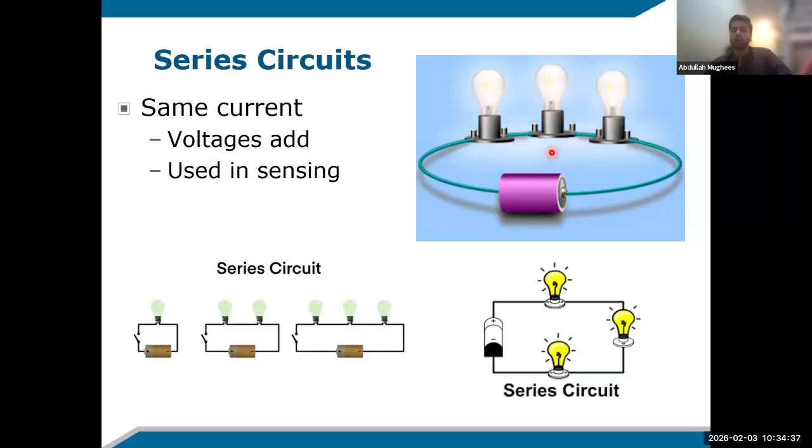All of the things are connected to each other, and they all glow perfectly with the same brightness. But the problem with this series circuit is this: if one of the components is faulty or you detach it, the whole circuit goes off. The whole circuit goes off because when we remove this third bulb, as shown in this animation, the circuit is now open. So the left hand side of this bulb is not connected to the right hand side of this circuit. So there is no flow of current through the air, right? So in a series circuit, if one thing goes off or something happens to it or you remove it, the whole circuit does not work. It does not blow off, but it does not turn on because it's an open circuit now. And we saw that for a circuit to work, we need it to be a closed circuit. So we solve this problem with a parallel circuit.